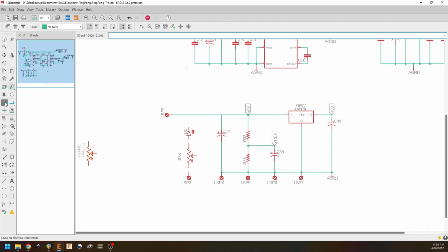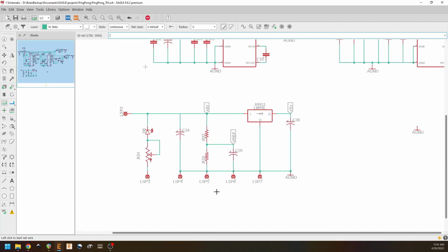We're going to wire it up as a variable resistor. That way this current limiting resistor can be dialed in for whatever color of diode we want. For example, blue ones, I usually use 22K. For red, I'll use something more like 4.7K. So it really depends. The water clear ones, I'll use really big resistors because those things are super, super bright.